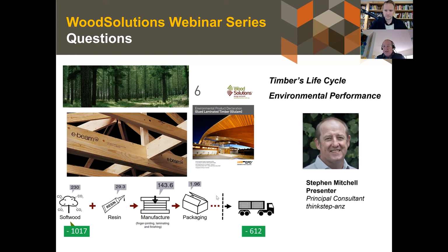I'm sure some of the other data might be applicable for other materials, might be really good, but for timber, people really struggle with timber sometimes in the life cycle assessment because of that biogenic carbon take up, and they get a bit confused. I'm not saying that they got confused, but that's why the data in EPDs, which is developed to international standards, and they're pretty strong and proven standards now, that's why I think you've got to rely on that sort of information for any scoping LCAs that you do, and any detailed design.